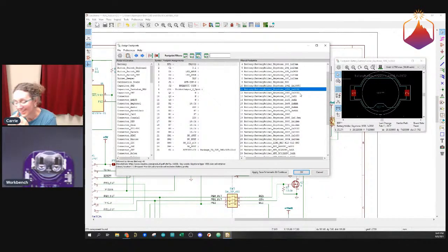We noticed this relatively quickly, but sadly we had shipped some out and had some customers that were unhappy with their thing falling off, which of course we immediately replaced. But we had to go through every single one and hand solder both tabs on either side to the board, and basically drown it in solder and make sure it was completely encapsulated and stayed down. That's a super pain in the ass. So I'm looking at this board and thinking, oh God, do I want to use the same battery holders again? We might run into the same problem. I don't think it was necessarily a bad board house thing. I think it's more that that connector and lead-free solder just don't mix very well.